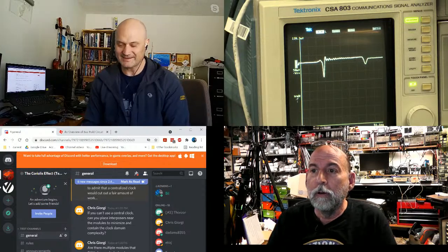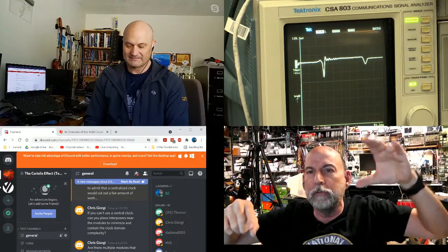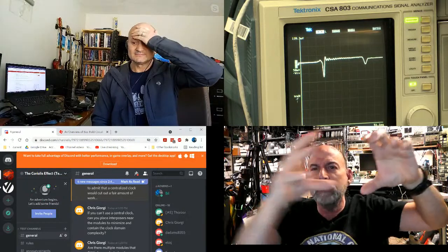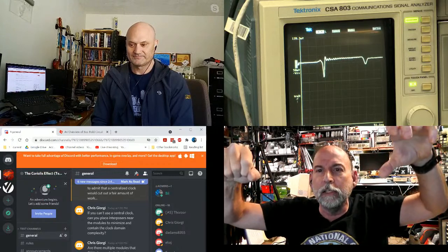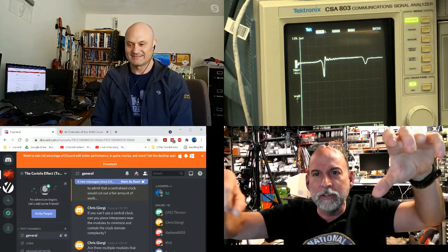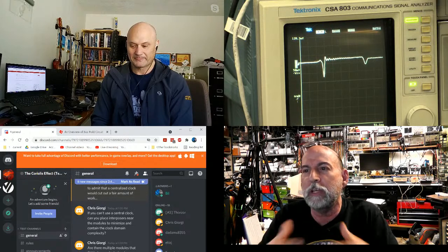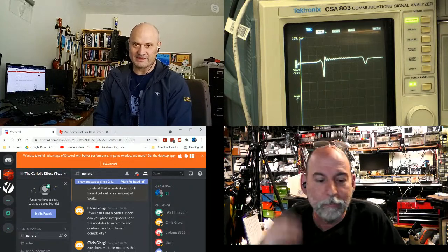And so there's techniques. So we had page mode, for example. Exactly. Where you get one row and then you go column, because you haven't had to recycle the whole row again. And the row driver is this big, huge thing, has lots of capacitance. So when RAS goes high and low, he's dumping and everything else. But once you do that, you can go column, and read out a couple, 4 to 256 columns in the same pre-charge cycle. And that's what created cache.